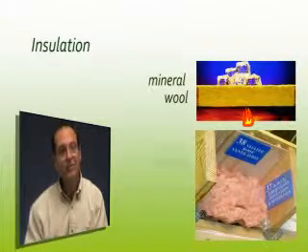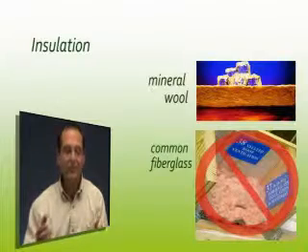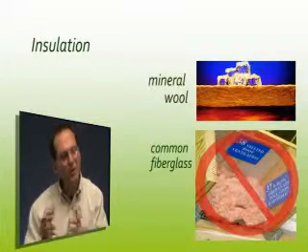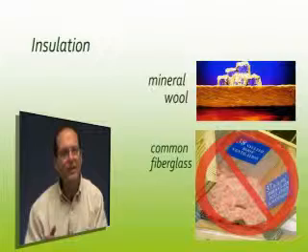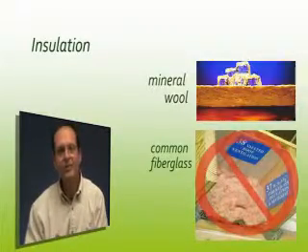Common insulation, fiberglass insulation, doesn't cut it. In fact, fiberglass insulation doesn't do you much of anything. It doesn't help a whole bunch with sound, a little bit with airborne, almost nothing with impact, and it doesn't do you any good with respect to fire.